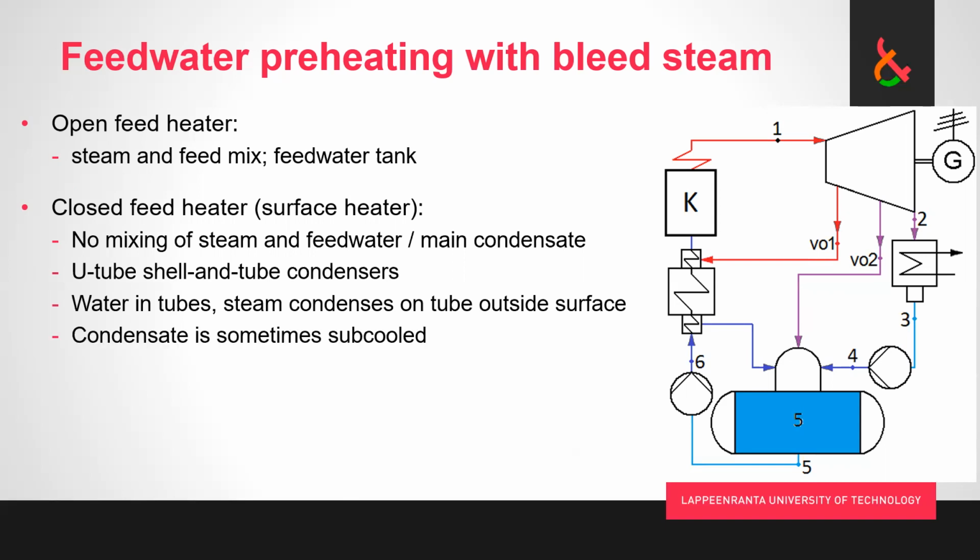Sometimes we might want to intentionally subcool the condensate. So this is typically happening, especially in these so-called high pressure preheaters. High pressure preheaters are the ones that are after the feedwater pump.